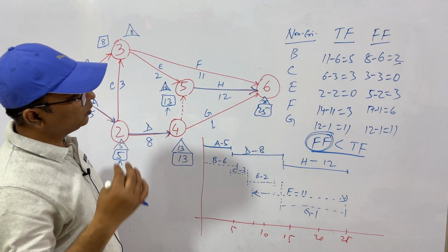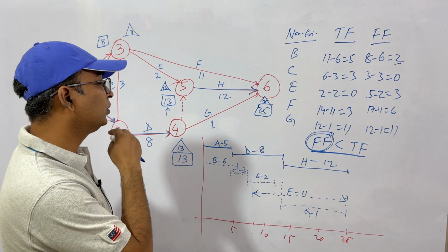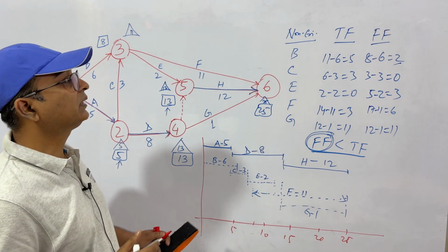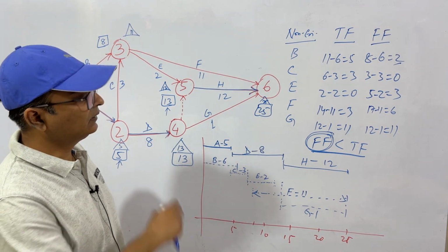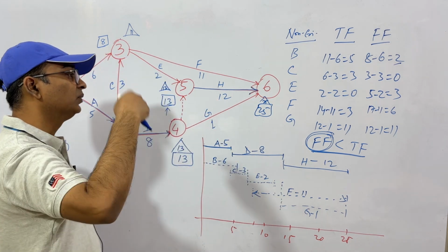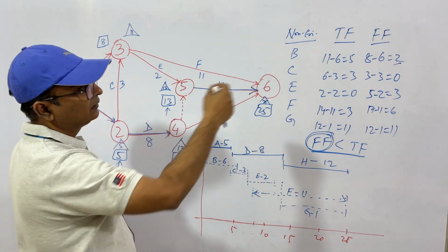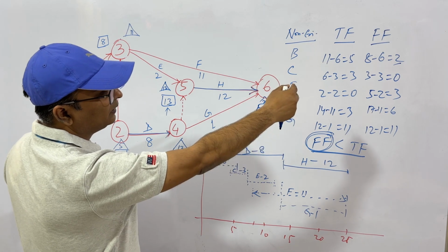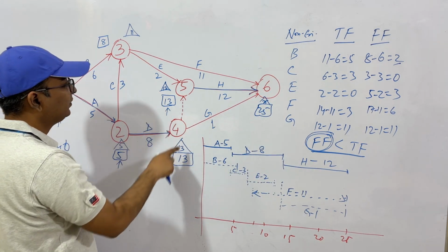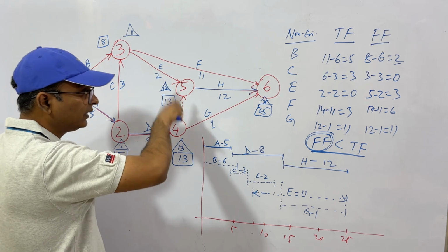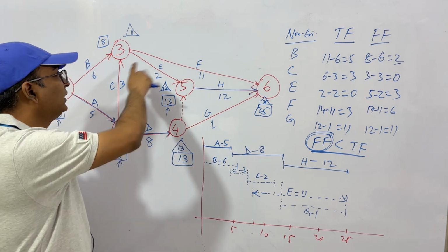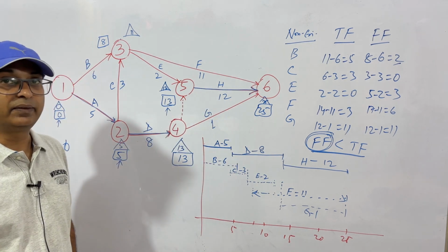So this is all about critical path method. I told you how to define the activities, how to have a network model of the whole project, then how to compute different timings, then how to schedule, and how to find free floats, so that you are able to design feedbacks. Then your non-critical activity should be delayed maximum by these number of days. If it is delayed, then you must create feedback. You'll need to reschedule it. The days will be delayed, but you need to work on each and every node and each and every activity. Clear?